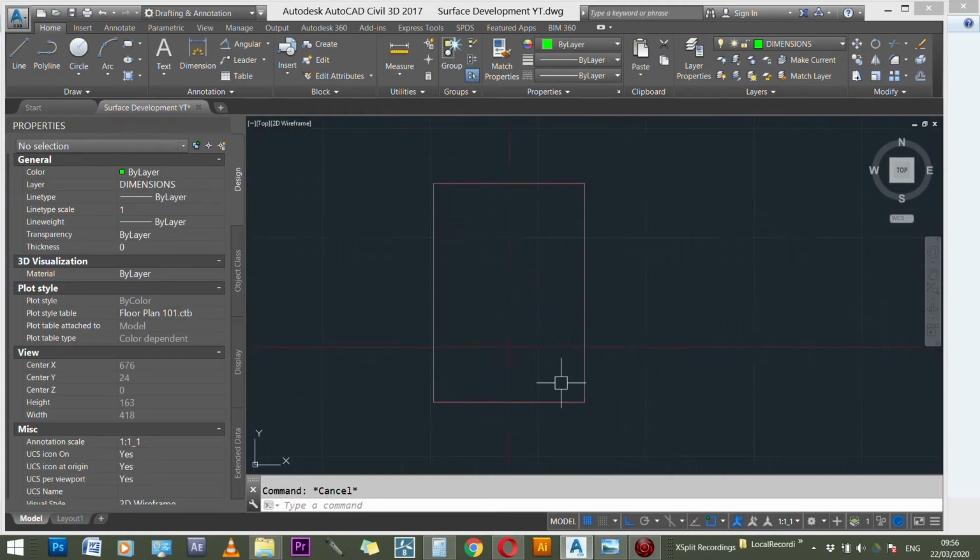That's it there. And now what we're going to do is we're going to offset 30 millimeters up from the base to this point, and then this gives us an opportunity to pitch our angle at 30 degrees. So I just grab a line, pull it to the right, and then I'm going to hit the less than sign and then punch in my 30-degree angle, and then I just flick this line slightly above the offset line of 30, and that's my 30-degree angle.